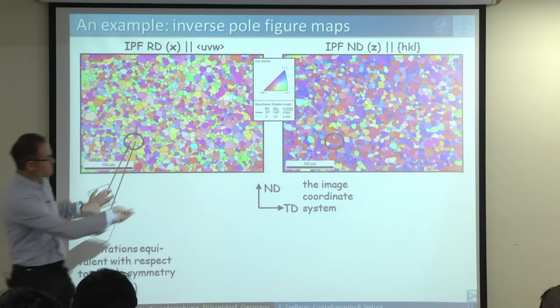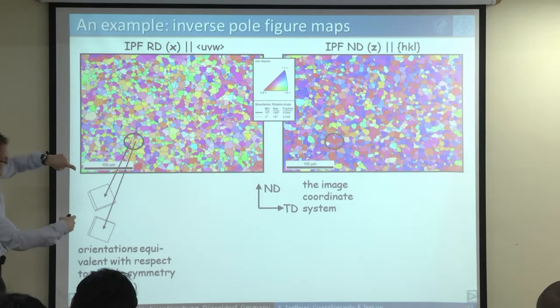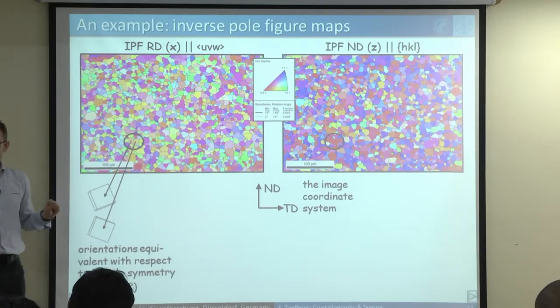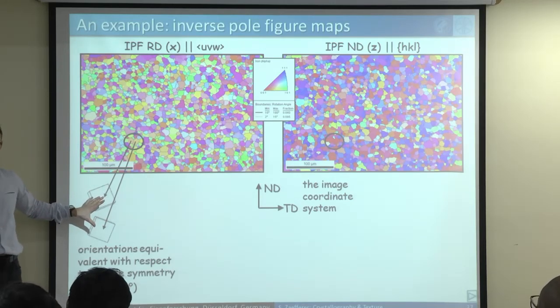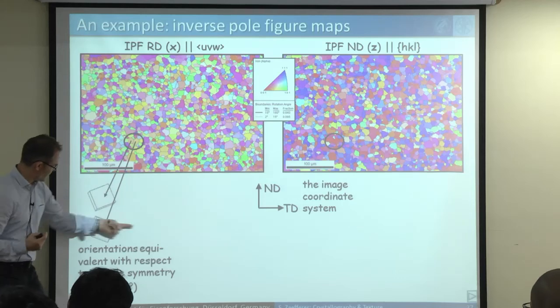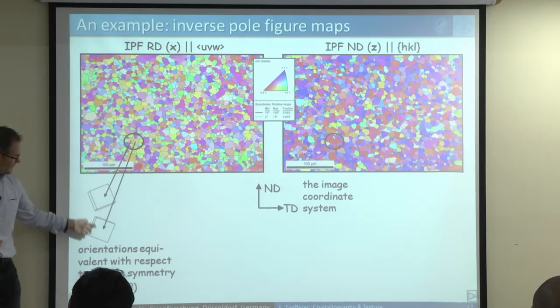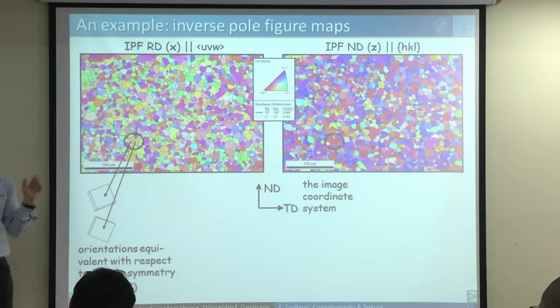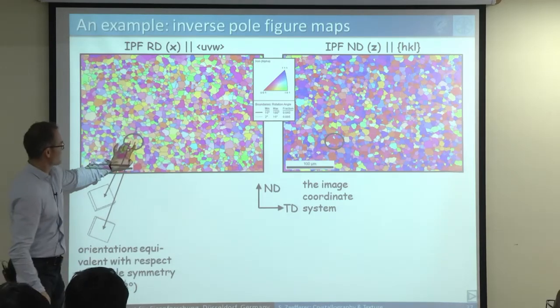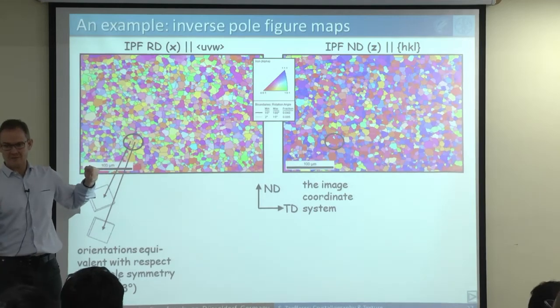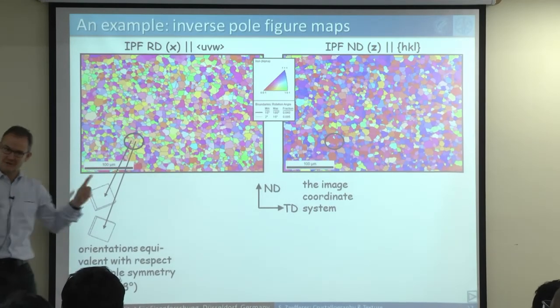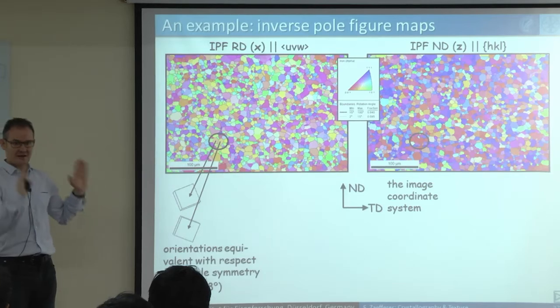And I combine both with a 0-0-1 direction here. So in this case, we are getting symmetric directions, but not identical orientations. We are getting identical directions for this one and this one, but the combination still leads to different orientations. So same color, but nevertheless not the same grain orientation. Symmetrically equivalent, but not identical.